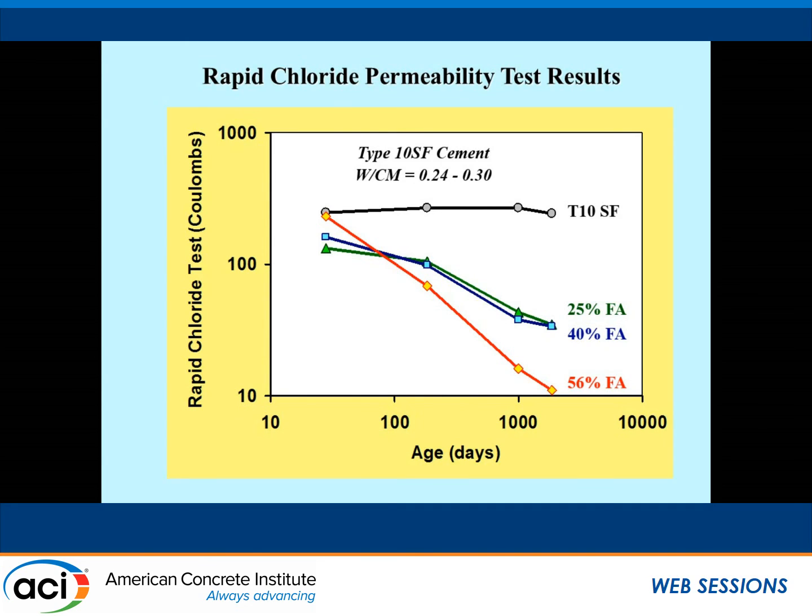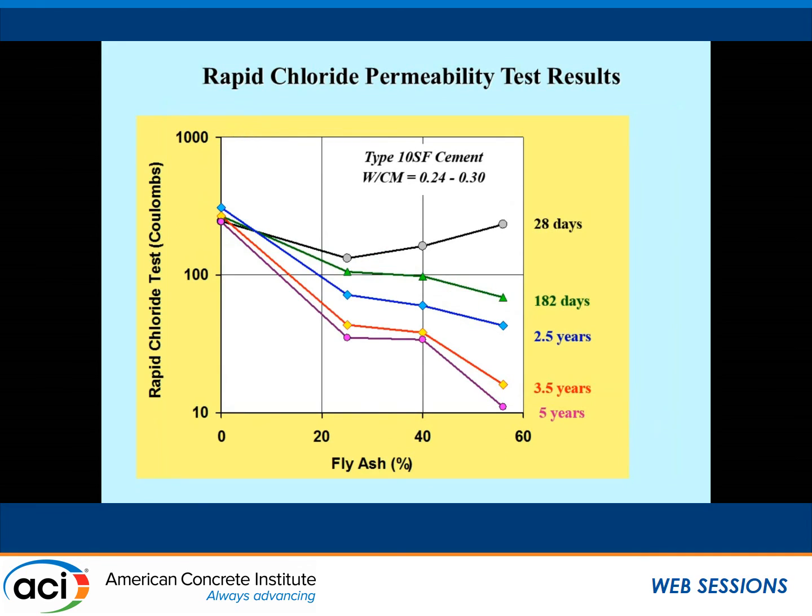I mean, it really is a very, very high level of chloride resistance. I think we can actually make concrete nowadays that is totally chloride resistant. We just have to stop it cracking. That's the next challenge, right? And in fact, I did say that 10 years ago when I showed this data last. So we still haven't got there to make crack-resistant concrete.